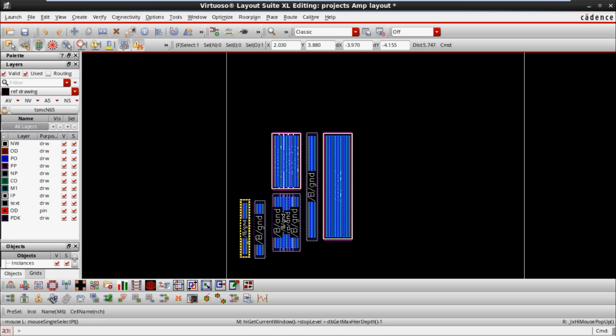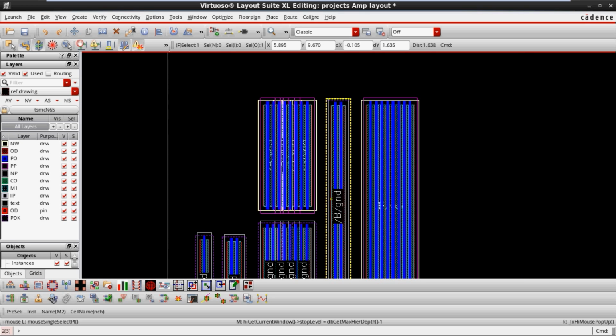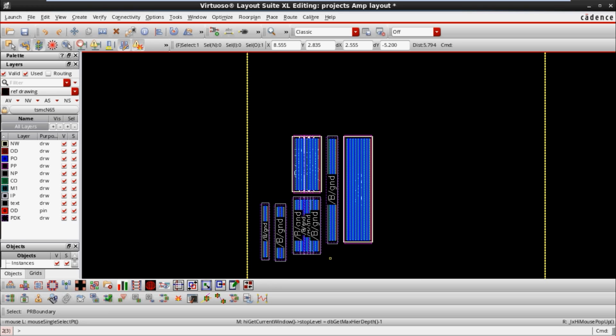That's why I have converted the devices from 19.6 or 19.8 to 4.8, and I have converted the devices into 4 finger, 2 finger. This is a methodology to optimize the area, so we can achieve our exact square shape or rectangular shape of the aspect ratio.